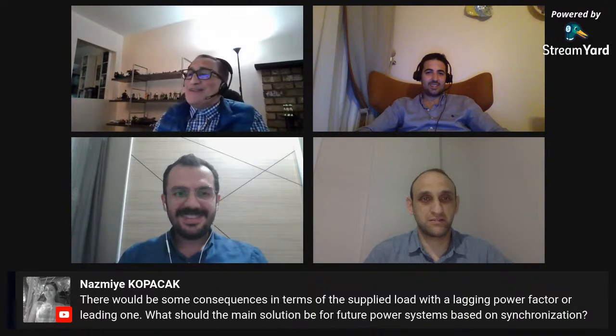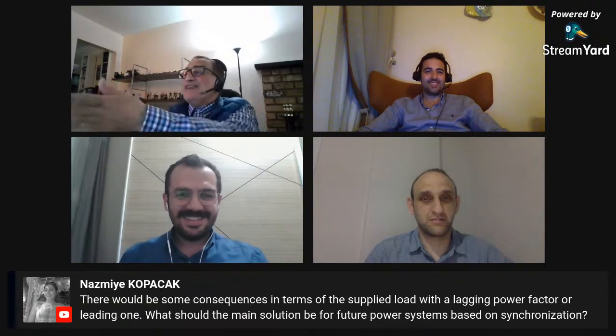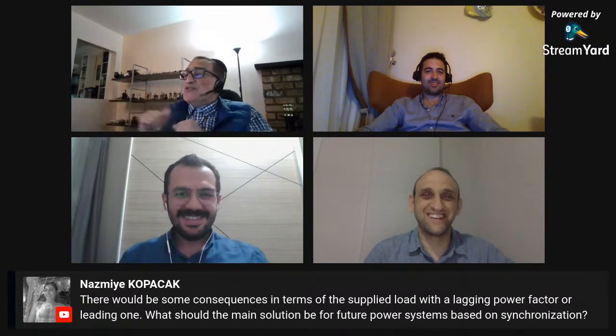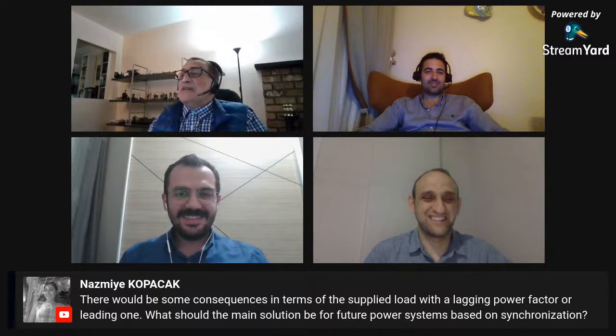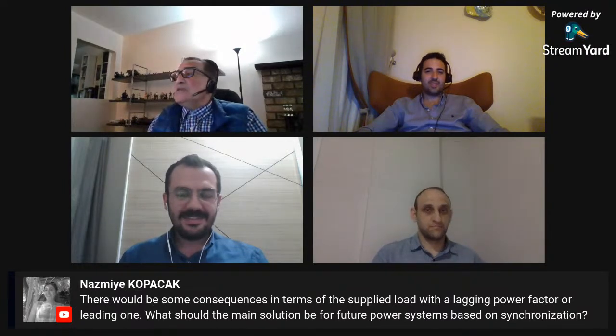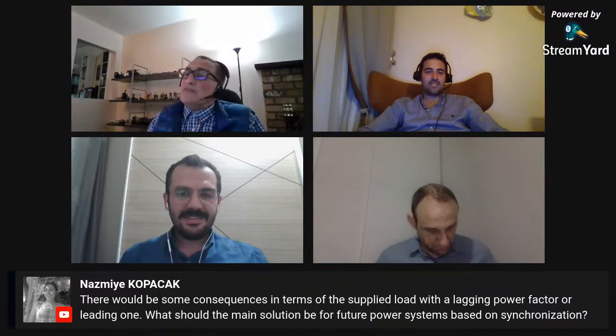First, I have to make sure that I understand which one you call lagging and which one you call leading, right? Because you can look at it in a different way. I can say it's leading, and you say no, it's lagging. So let me make sure that I understand. Let's say the current is lagging the voltage. If that is the case, what would I call it? System is not fully compensated.